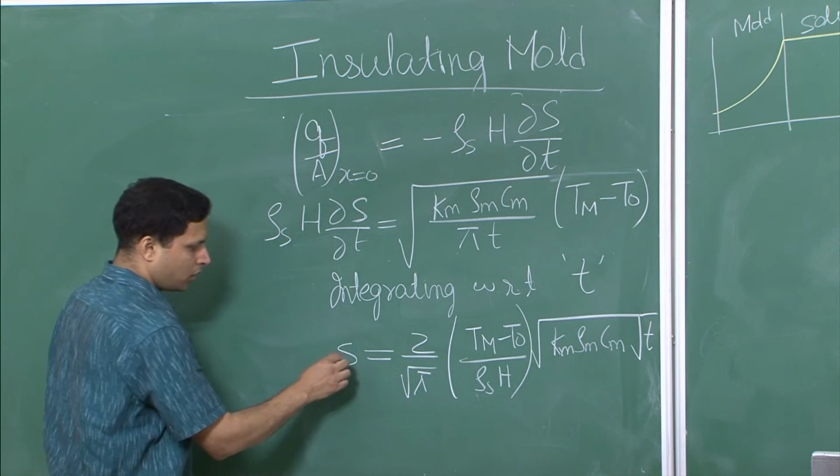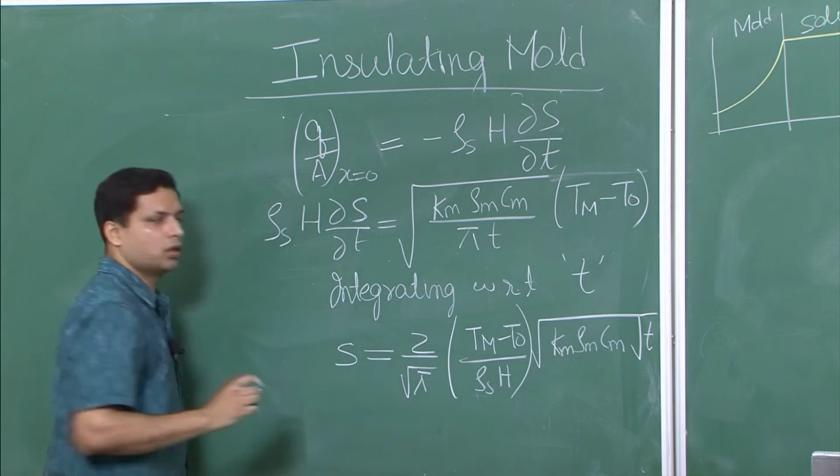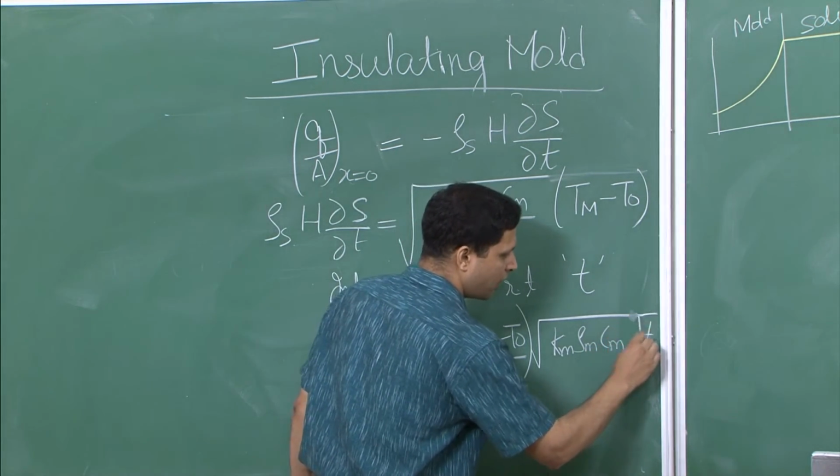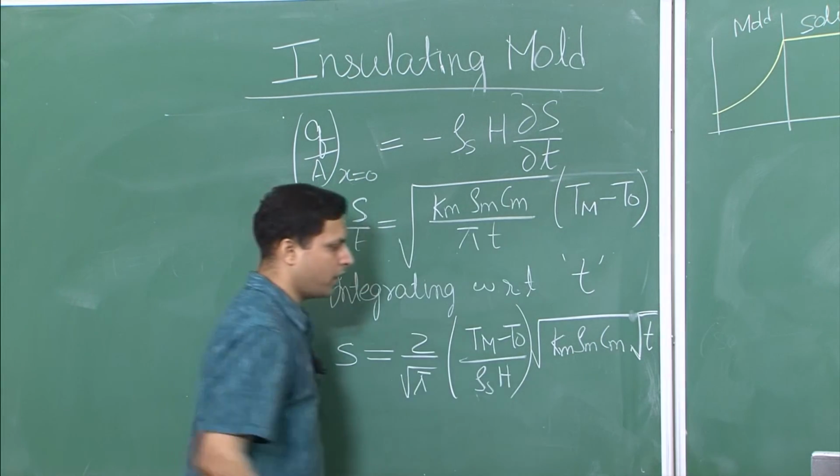So, this S, the length that has solidified, can be obtained in terms of time t. This is proportional to square root of t.